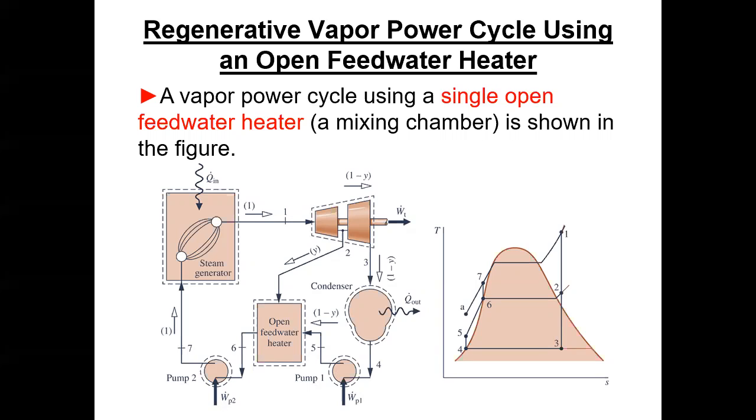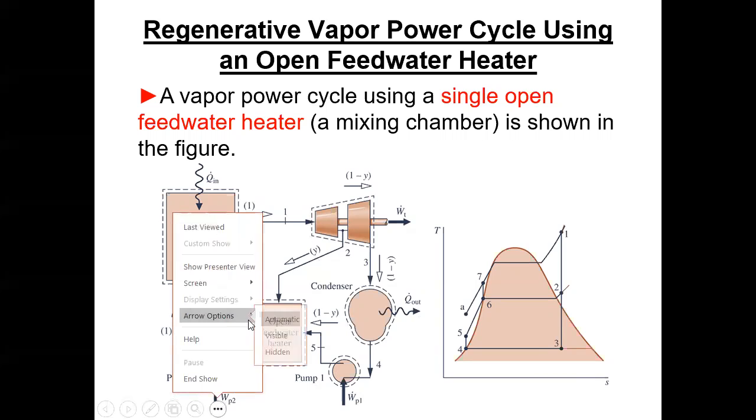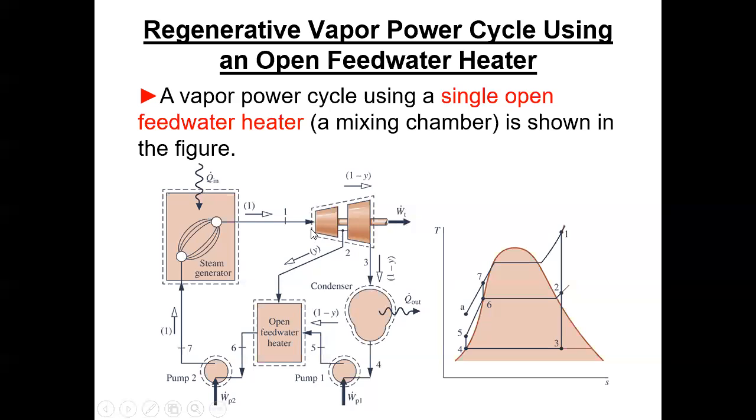And so notice when you take into consideration the amount of power that's generated, we have the full mass flow from 1 to 2. All right, from 1 to 2. But then from 2 to 3, I'm going to take this 1 minus Y1 and multiply it by the enthalpy difference to indicate that I only have 80% of my mass flow. Okay, so we'll see that.